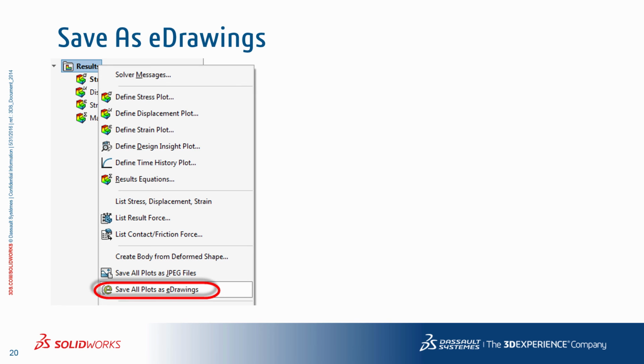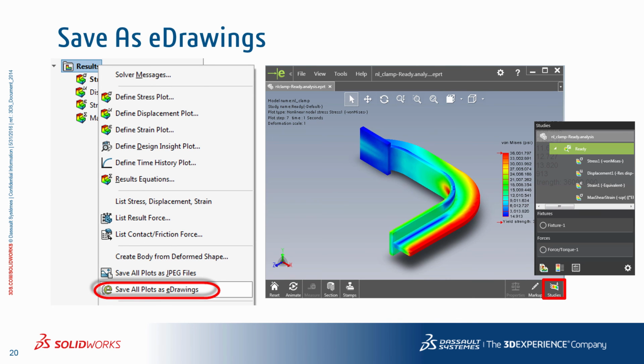You have the option to save each plot separately into an eDrawings file or save all plots as shown here. I prefer to save all the plots into a single eDrawings file. That way it's much easier to share and collaborate the entire set of simulation results in a single shot with someone who may not have the tools.